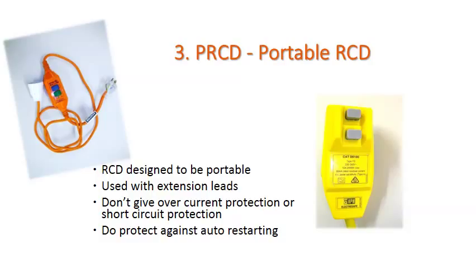PRCD, portable RCD. You more than likely have seen one of these. You take them out, plug them into your socket, and it gives protection for whatever it is you plug into the PRCD. It's designed to be portable, used with extension leads. Sometimes it's incorporated into the extension lead. They don't give overcurrent protection or short circuit protection, but they do generally protect against auto restarting. If the power goes off and power turns back on, usually the PRCD has turned off and won't start again until you push the reset button.